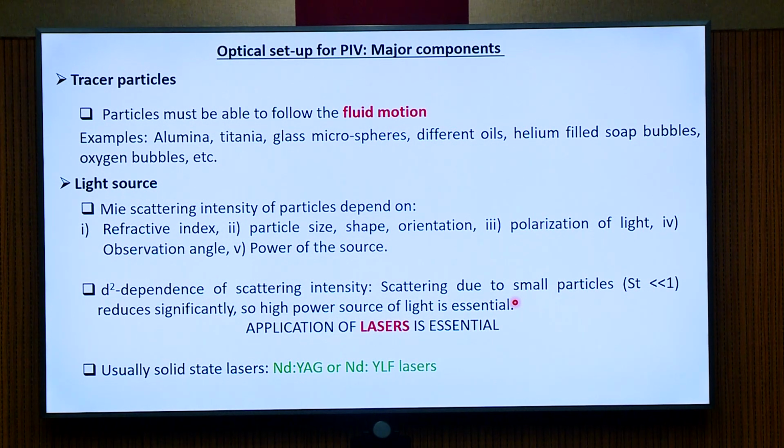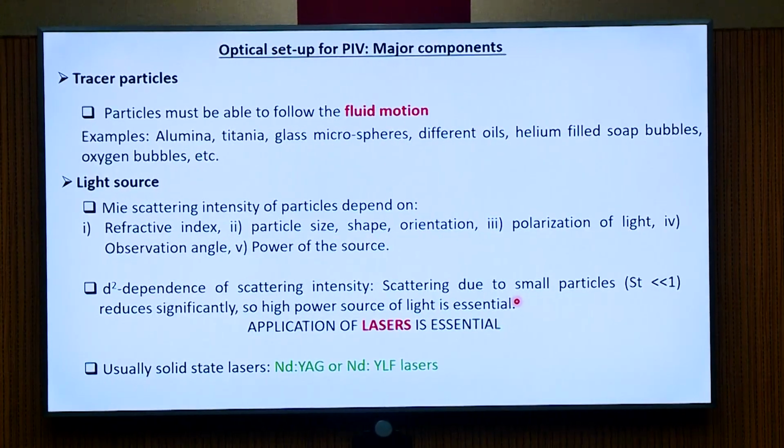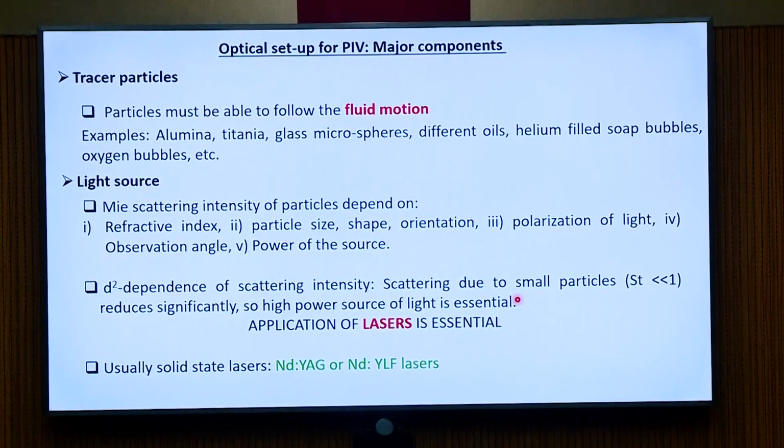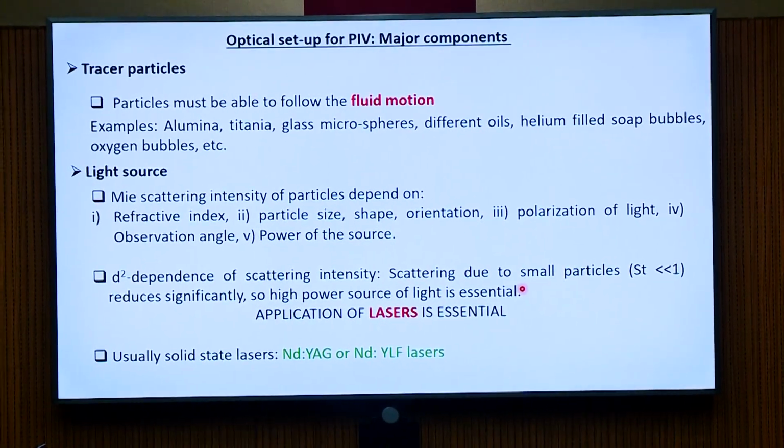Now, you know that turbulent eddies themselves have a wide spectrum. You have large scale eddies that scale with the physical dimension of the flow, while on the other hand, you have the Kolmogorov scale eddy, which is the smallest eddy that is possible, which is much smaller than the large scale flow. So how do you know which eddies it can track?